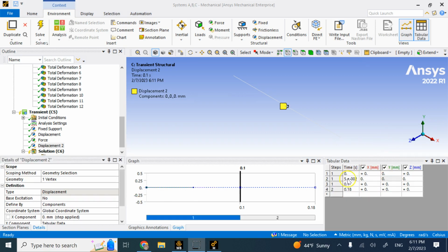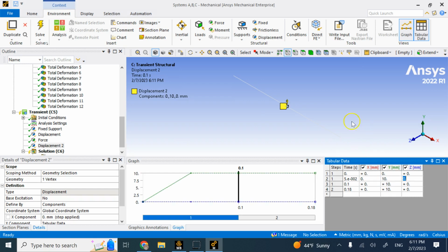values, right? Now here I add one extra point at 0.05, and remember this was the time step for the first part of the simulation, the static simulation. So initially I set my y to 0, but then at this time step I reach the final value that I want, and here I assume that I want to move that point 10 mils up, and then keep it at 10 mil, right? So this is going to be the data that I provide for the y motion of the middle point, basically moving the middle point 10 mil up and then letting go.